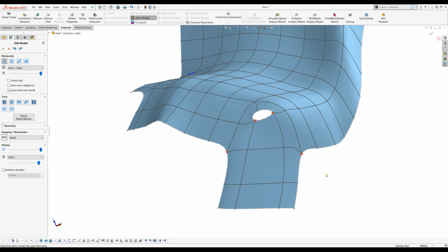Now, it's a good example. I probably will repeat this again when we have other cases, when we do the real remodeling. But in some cases, you may end up with something which is called a 3-point hole here, like this example. And it's really hard to close because our surfacing requires 4 sides.